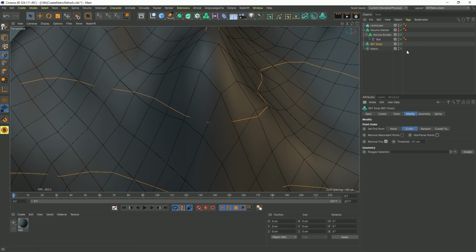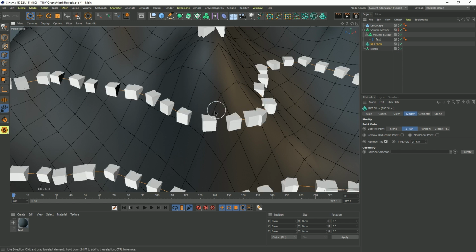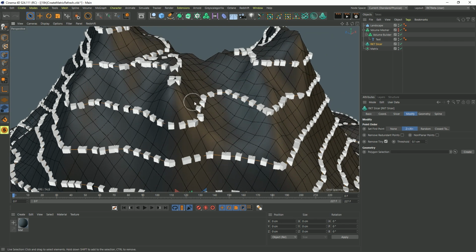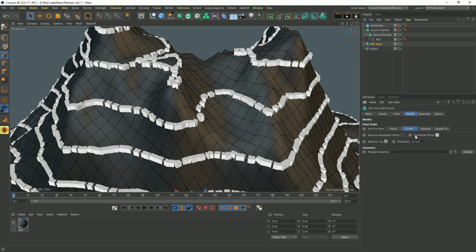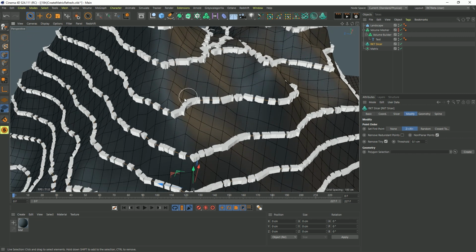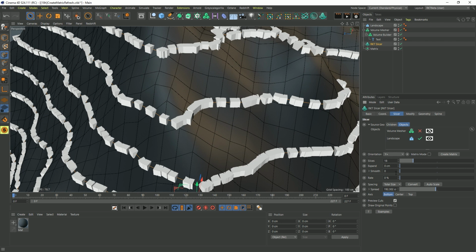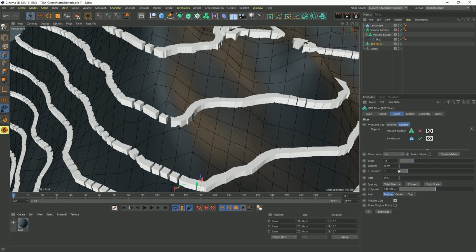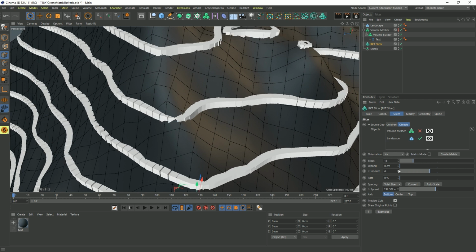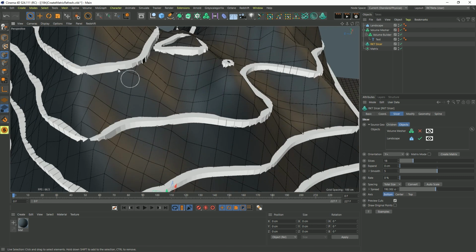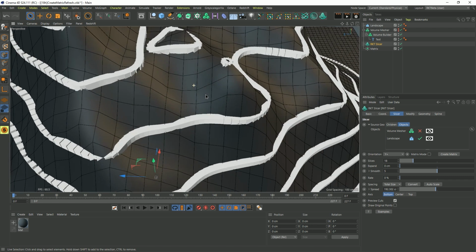So to show you, let's turn that off and create the matrix again so you can see where all these matrix points are. But on an object like this, by turning on non-planar points, it's almost going to double the point count. You see how many more points there are because it's pretty much like everything's getting triangulated. Only if it needs to, but a lot of these need to. Keep in mind that those points will be taken into account if you were to move into the smooth parameter. So if we add some smoothing layers on there, you can see how even all of them begin to get as they average out based on where their neighbors are.